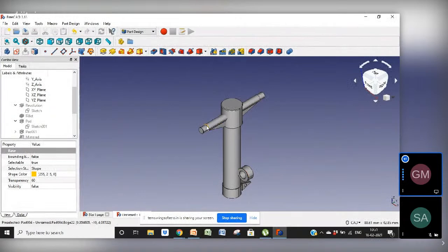Now here would be ball joints. Then the housing of that ball joint, here the drag strut would be connected to the main aircraft, and after that here would be the pneumatic cylinder and piston. Here the torsion links, and the piston inside this with another torsion link, and those torsion links are joined to each other. And on that piston head down there would be the wheel assembly. And this is how we have completed our landing gear. All the components are completed and this landing gear is complete.